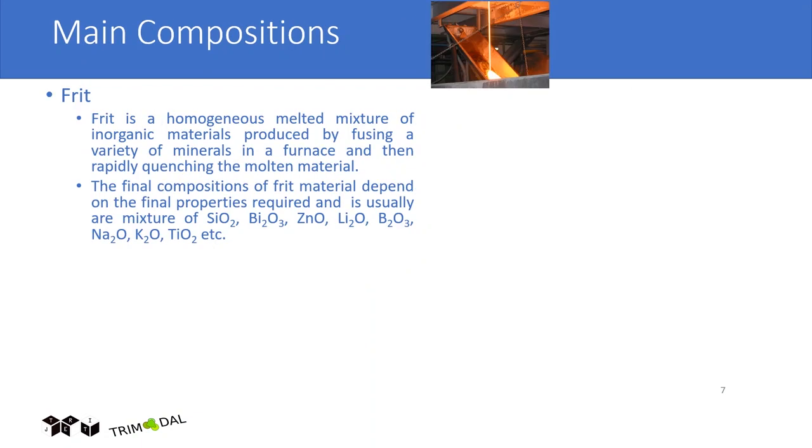Okay, so if I take that, the frit now becomes very important because it's a complex mixture of compounds. It's cooked up to about 1200 in the furnace and then rapidly quenched, right? And the property you want in the frit depends on the silica plus all these components, which define what type of property. So the frit for automotive would have a completely different thermal expansion coefficient than you would make for home appliances, because of the different thermal expansion and contraction cycles.